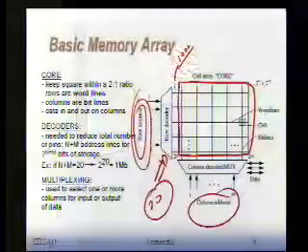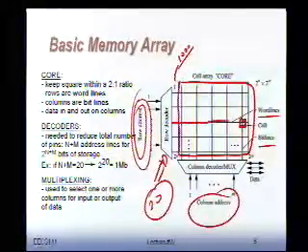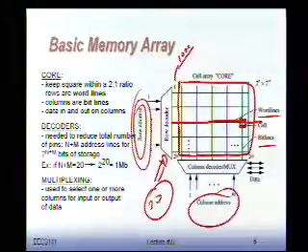Some more nomenclature, or basically some more definitions to be aware of. So you have a cell here. Your row address comes in, you select one row, and you have a wire that basically goes high. That wire that addresses the cell in the horizontal direction is called a word line. A word line is this horizontal select line that will say, hey, you are on, you're off.